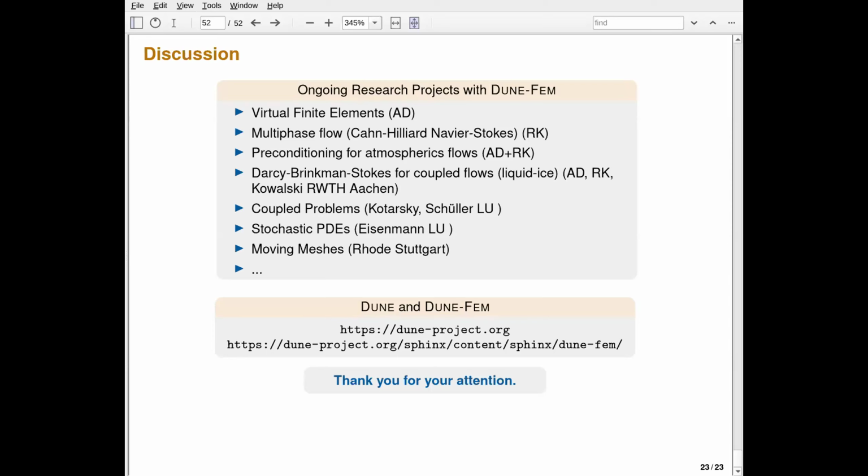And we even have implementations for very unstructured grids where you no longer have a reference element, so you don't really know what the geometric structure is other than that you're given a volume and the number of nodes. This kind of Voronoi type can be handled, but of course you're then a bit more restricted in the type of discretization that you can use.